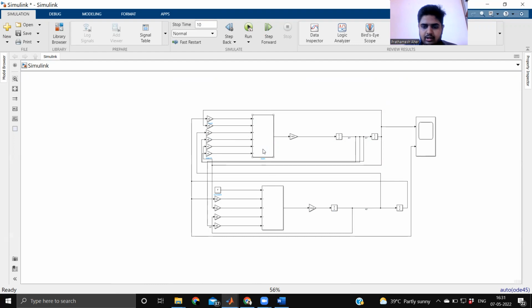The add block is a subtraction input. Specify the following characters in this string: the character vector contains a plus or minus for each input port, with a spacer between the ports. For example, this is a plus and this is a minus value.